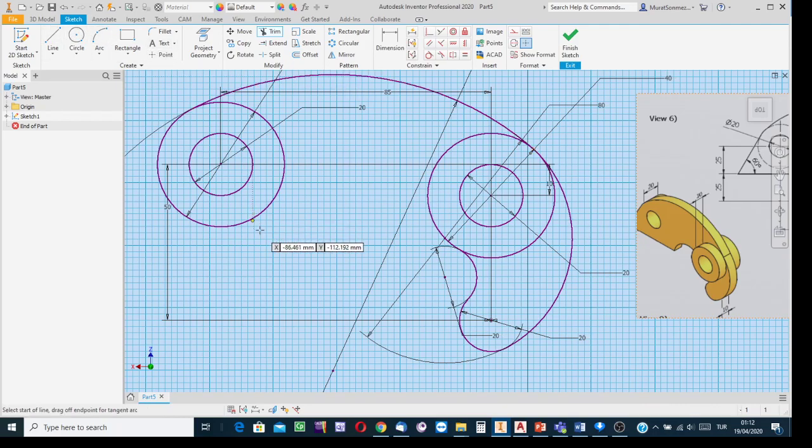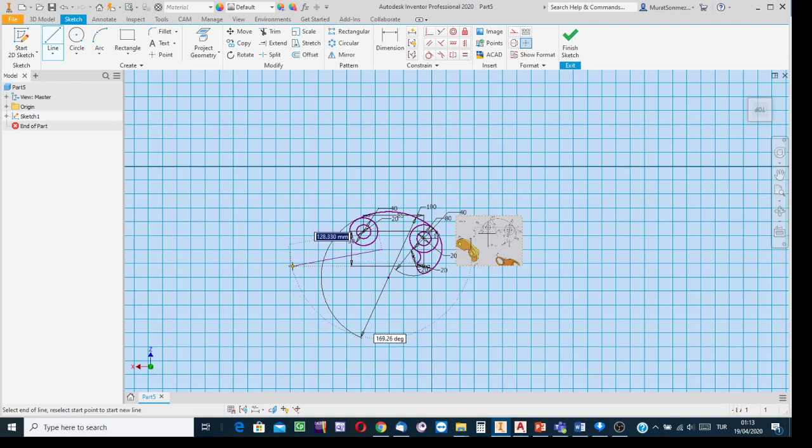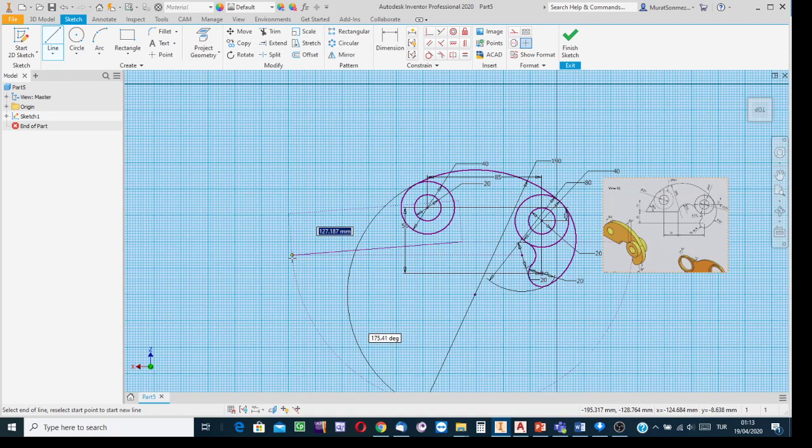Create the line arbitrarily first, locating its terminal point on the correct side, with a length larger than its order of magnitude. In doing this, avoid having dotted lines between the cursor and the characteristic points of the already created entities.